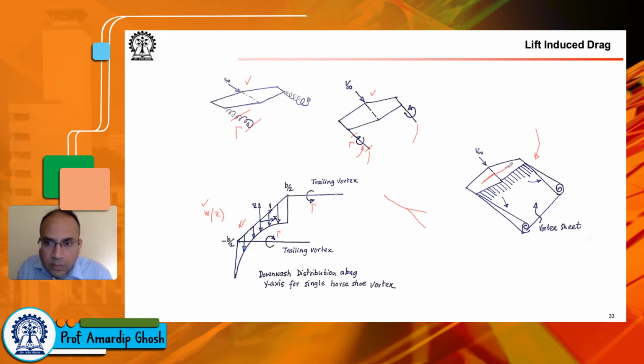But eventually, these vortex filaments influence the velocity field on each other, and I think it can be shown analytically, or at least computationally, that these things will actually wrap up into these large contrails eventually. So these vortex filaments will eventually get rolled up into these large vortex contrails, eventually giving the same description like this at a large distance.